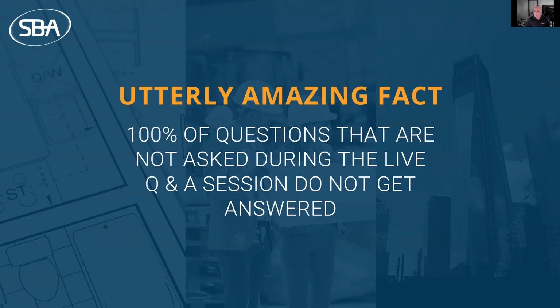Have I ever seen where BACnet MSTP at the end of line is looped back to the start of the daisy chain? I've seen a lot of crazy stuff, but that completely violates the RS485 standard. But yes, I have seen stuff like that before. I've also seen a lot of T-taps.